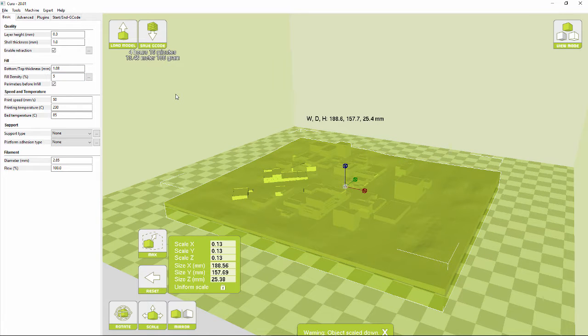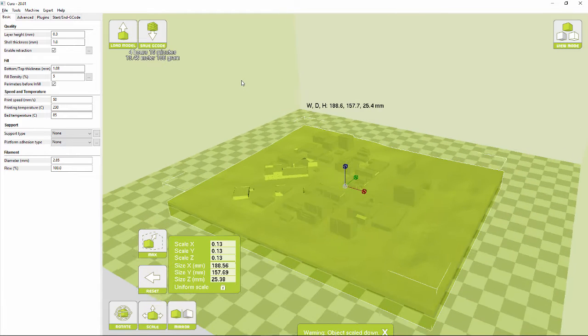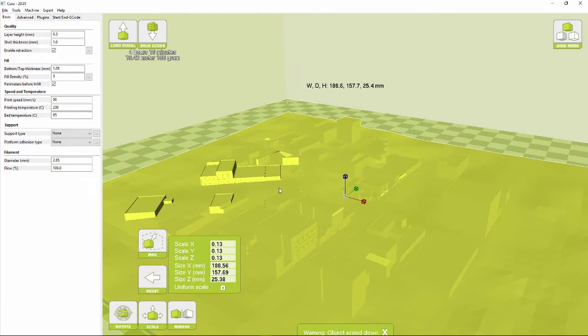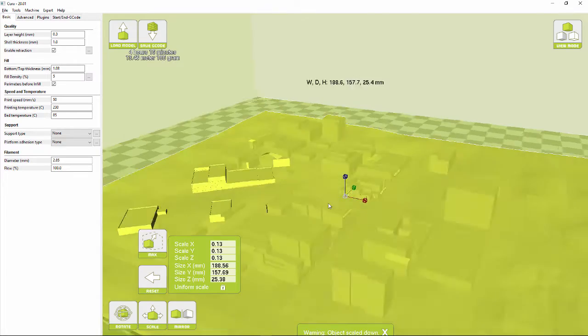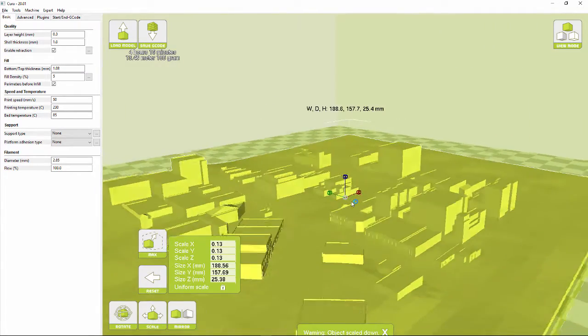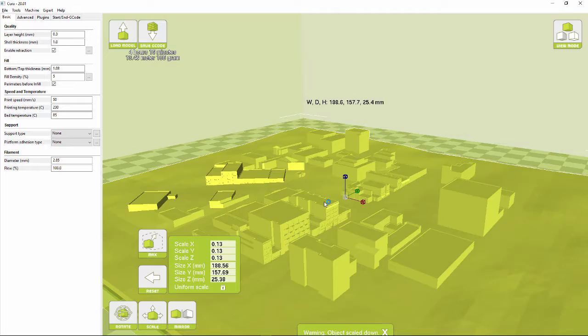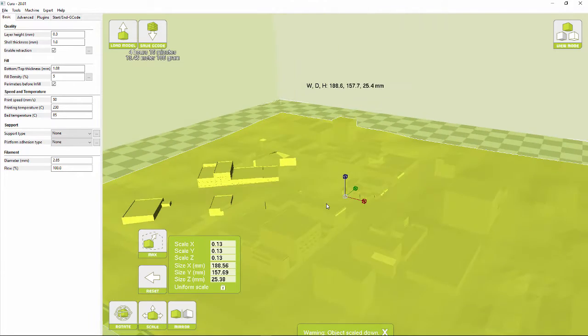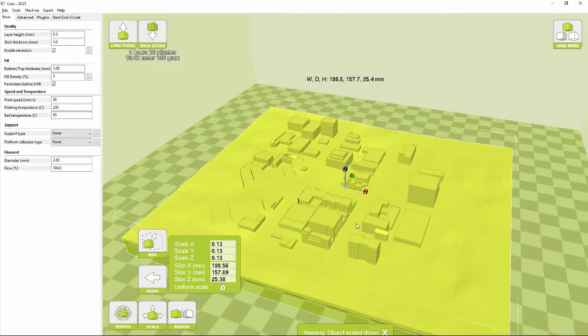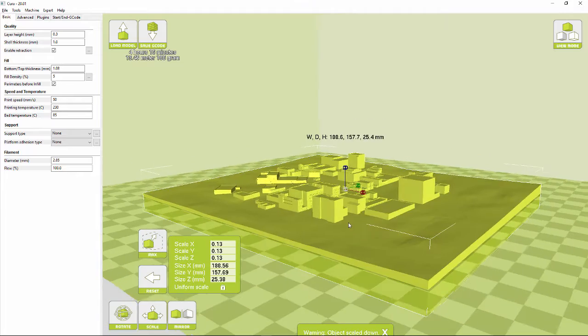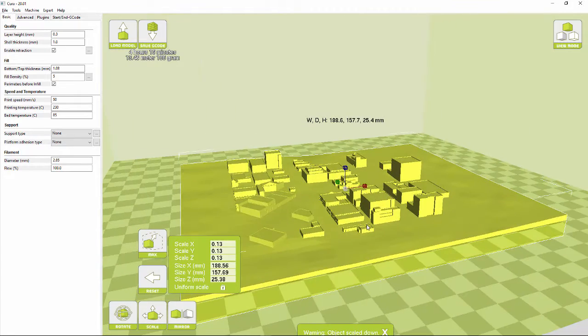Typically in architecture, we're either printing with PLA or we are printing with a polyester. Both of them are low off-gassing and recycled. The PLA does a little better job in terms of not drooping as much whenever there's an expanse, which we have often in architecture, window openings, door openings, things like that. The polyester is just super consistent and performs exactly the same way every time we print.